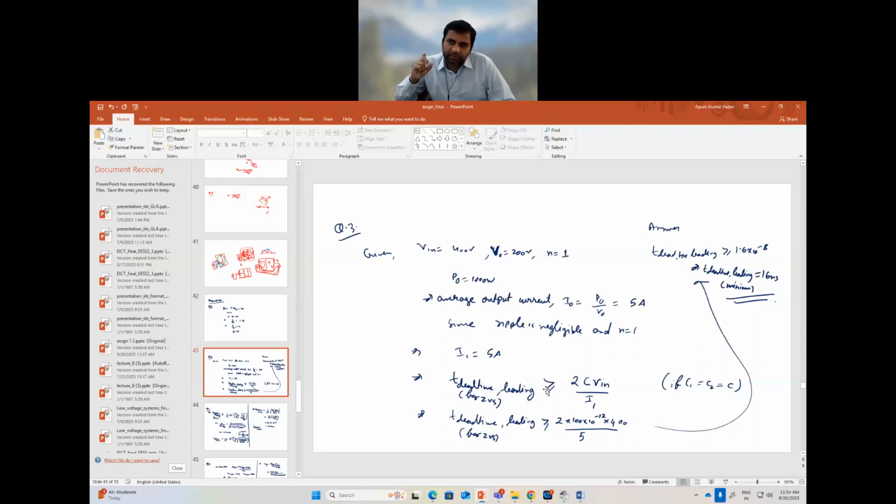In the question it is given that we assume the necessary condition, which is that the energy of the inductor, which is there in the current going through the inductor connected at the pole of the half bridge, must be very much greater than half C1 V in square plus half C2 V in square. So that condition is met. That assumption is already given. Now we have to find out the required dead time such that the current which will fall down because of the dV/dt is due to the current which is coming out of the half bridge.